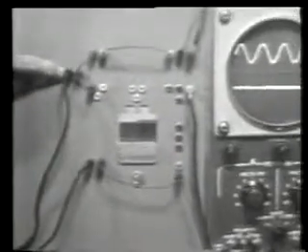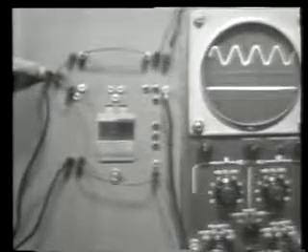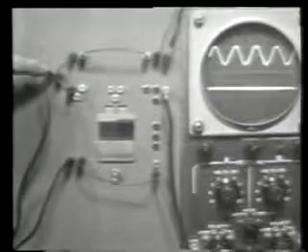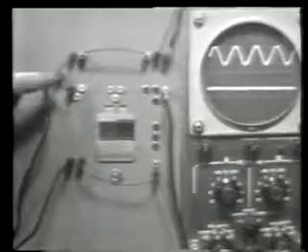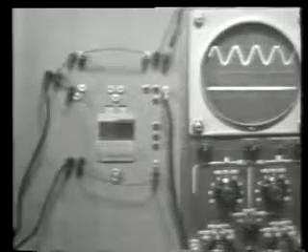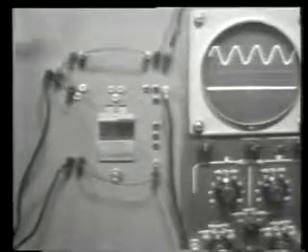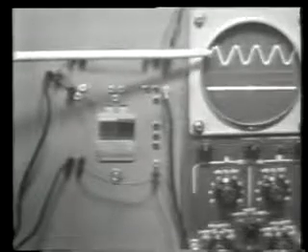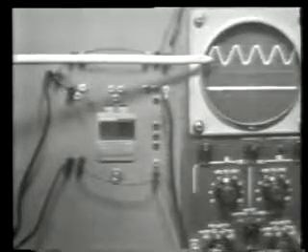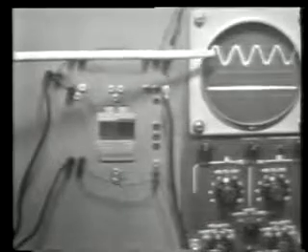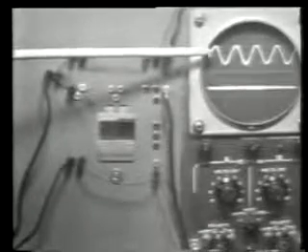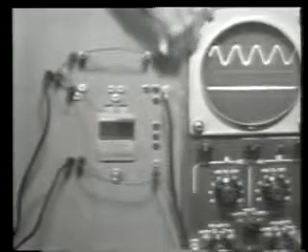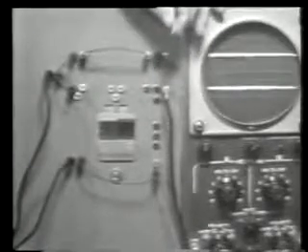up to this connector. Now from this point, the 10-volt signal is supplied to two places, the upper connection here and a lower connection here. Now the upper connection goes directly over to this point, and as you can see is tied directly in to the A trace or the top trace of the oscilloscope. Now this shows or displays the output from the signal generator at all times, the top trace of the scope, and is connected with this connector to this point.